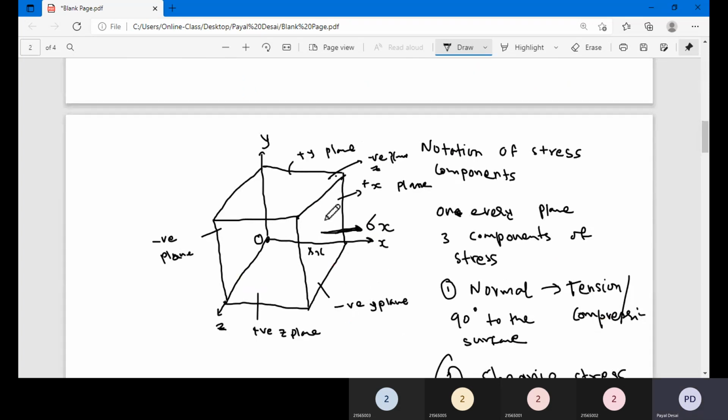Now the remaining two I can define in the tangential direction, because my delta p, which was in a random direction, I resolved the force, and then when I divide it by the cross sectional area I get the stress. On every plane I have resolved it into three different components, and then consequently I am finding the stress. In civil engineering also we write the components. Ultimately the resultant should vanish, because it is equilibrium, so the resultant should be zero. In elasticity, an advanced solid mechanics subject, bending moment and so on will come later, but first we will define stress and strain. As there is stress, there will be strain also, in every direction. So first we will define stress and then strain.